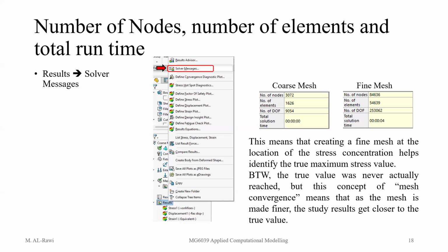In FEA, we tolerate a maximum error of 4.5% between experimental and FEA. More than that, we question it. Like that's for industry, for research. For study, we're okay with even 70% error. But in reality, no, that's too much. I mean, your results need more refinement.